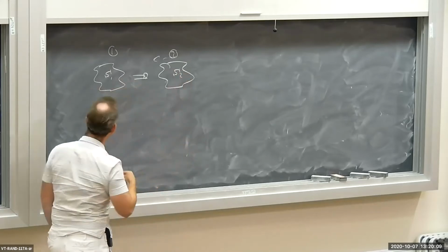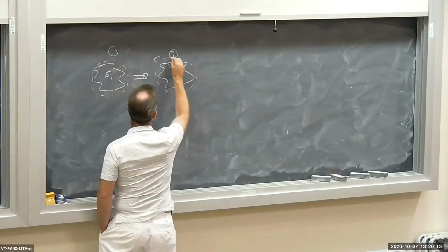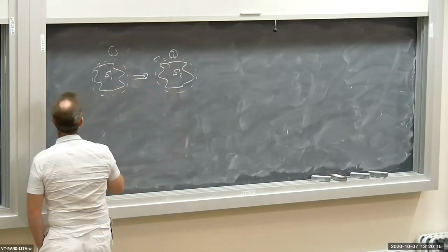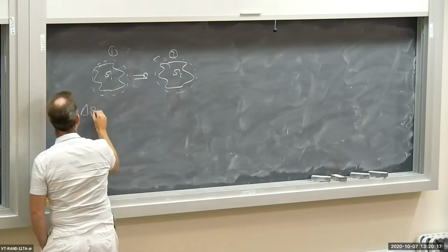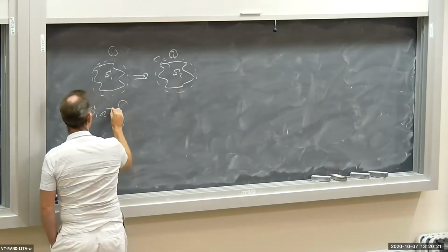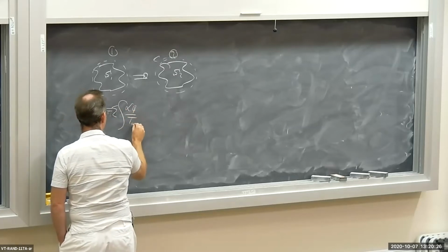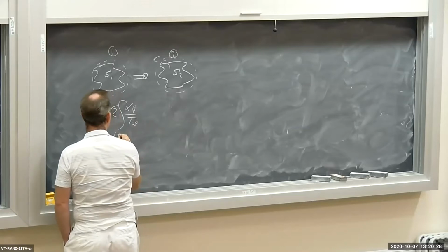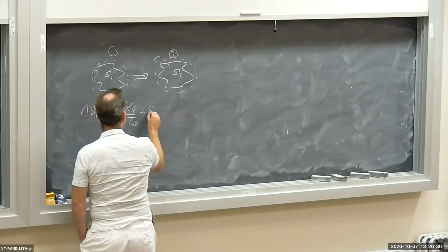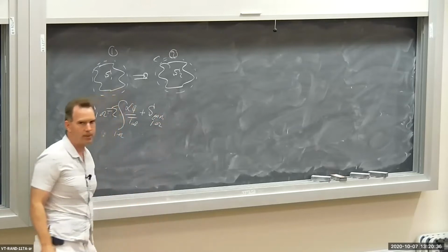So if we write the entropy balance on our system, it's a closed system, we see delta S from 1 to 2 is equal to the integral of del Q over the interaction temperature plus entropy generated due to irreversibility over the process, okay?